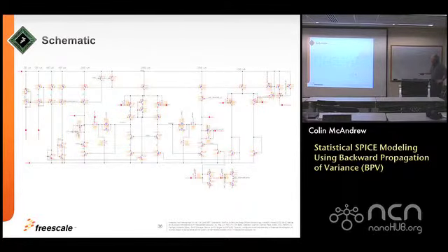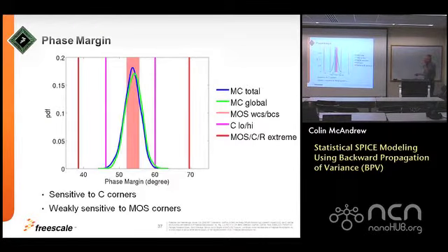So there are 47 transistors. It's a differential. This is the input cascoded pair. That's the output pair of devices. That's the RC compensation Miller feedback. And that's the common mode feedback for the circuit. And it's hard to look at. So it is a real circuit though.